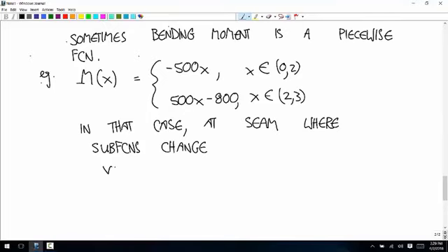First, the deflection using the subfunction from the left has to equal the subfunction coming from the right. That means that there's no discontinuities in the beam.